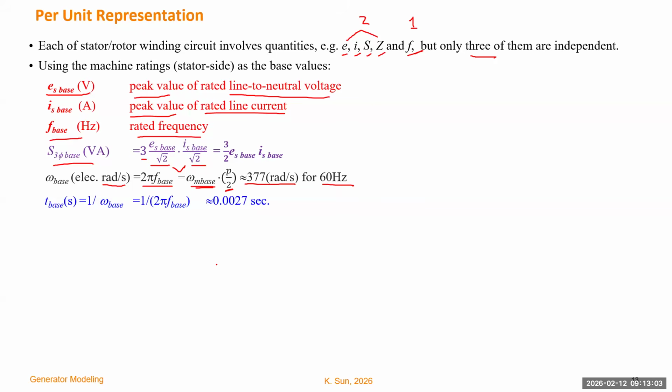When we derive the equations to model a generator, we want very simple equations. Sometimes if you know which parameter has the meaning of time, you can assume that the default unit will be second. But when the equation becomes more complex, it will be more convenient to treat everything in per unit. So then we need to define the base quantity.